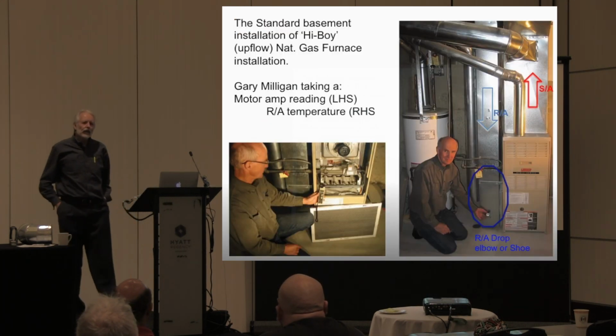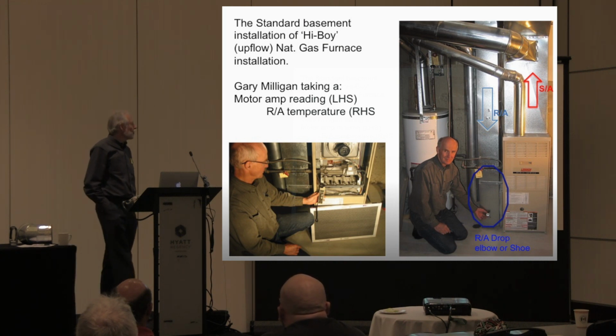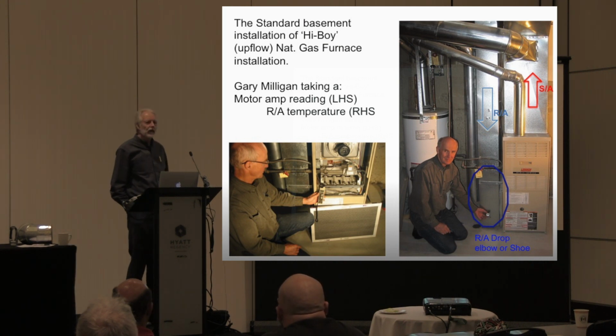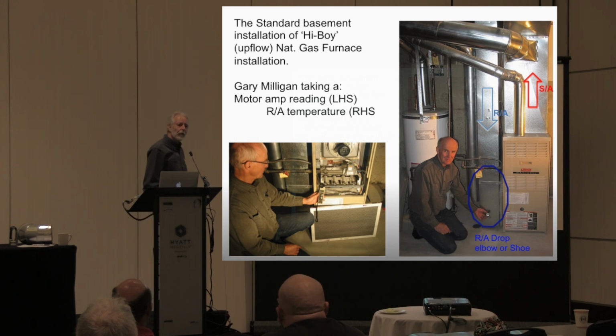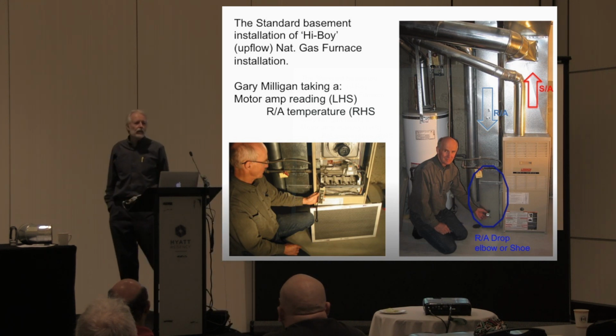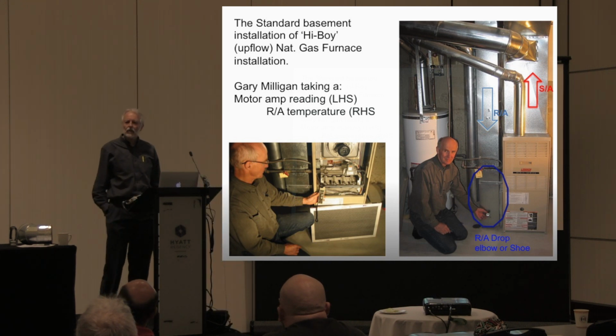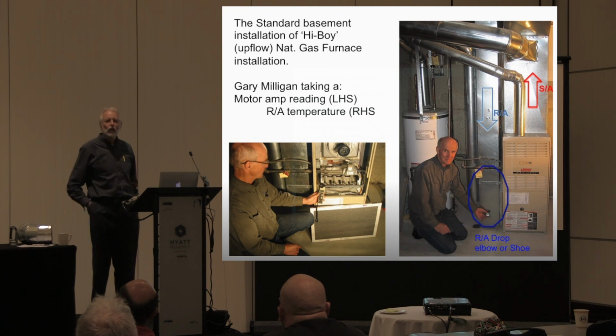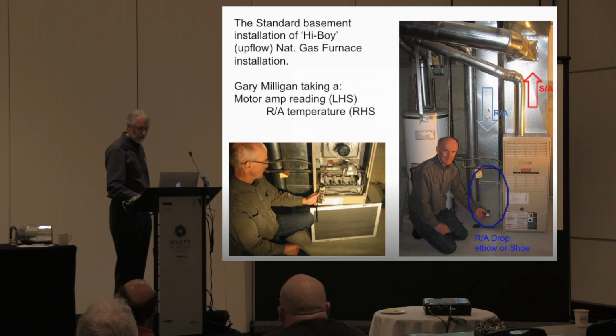In preparing the course, Gary and I wanted to make sure that this was very, very well grounded. So what we did is we measured piles and piles of furnaces for all the important parameters: return air temperatures, supply air temperatures, pressures, ammeter gauges, so you can find out exactly what's happening. There's absolutely no guesswork, and guess what we learned? Everything the textbook said in 1932 was in fact correct. Nothing's changed.